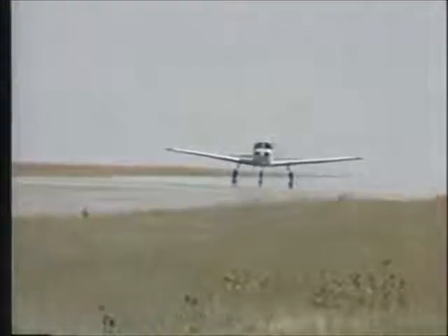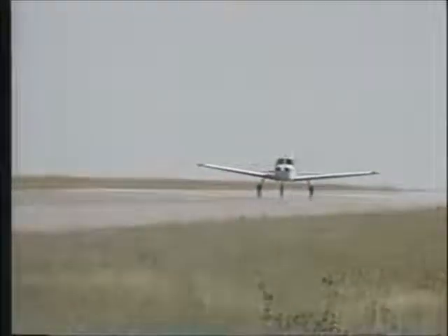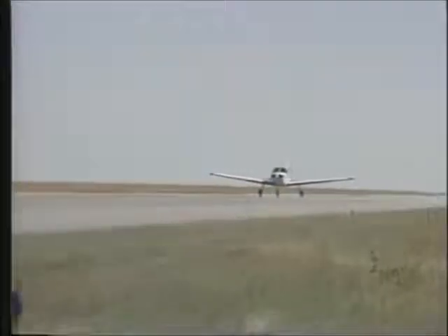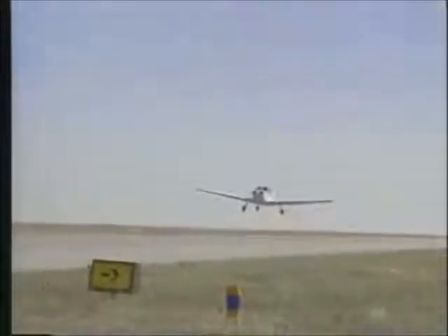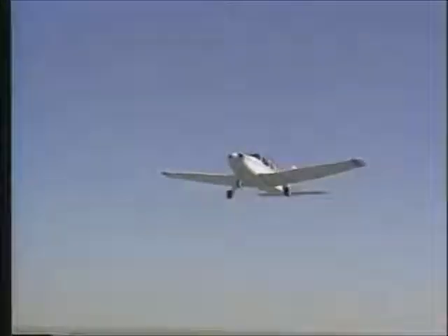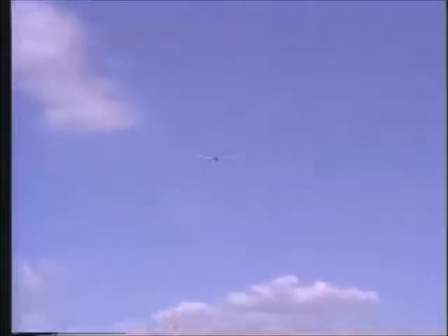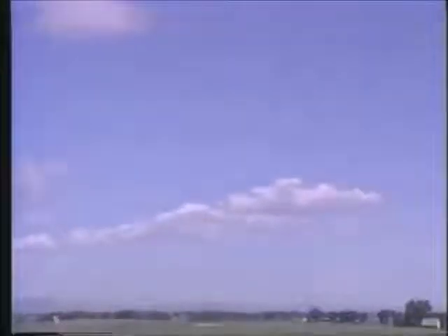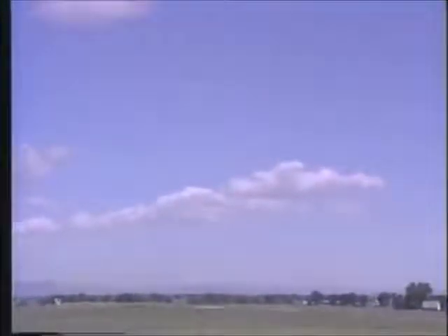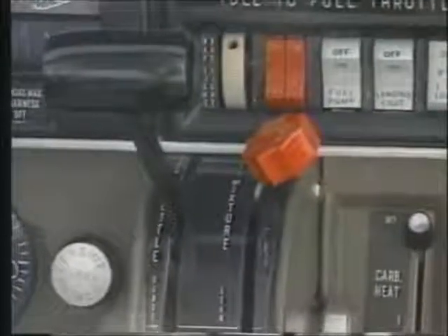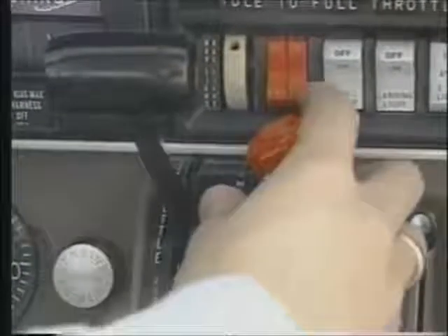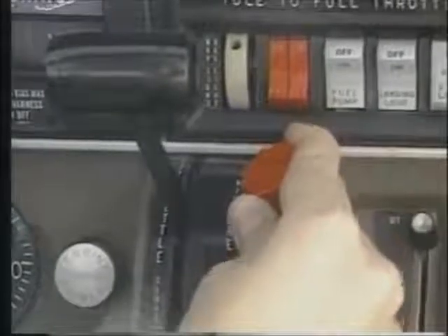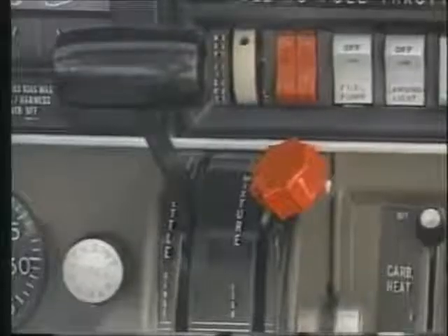position. But as you have learned, the density of the air decreases as you climb to higher altitudes. Subsequently, the density of the air entering the carburetor will decrease, while that of the fuel remains the same. This means that the mixture becomes too rich, or there is too much fuel for the density of the air entering the carburetor. A mixture control lever or knob is located in the cockpit. It enables you to adjust the amount of fuel to maintain the correct fuel and air blend at varying altitudes.